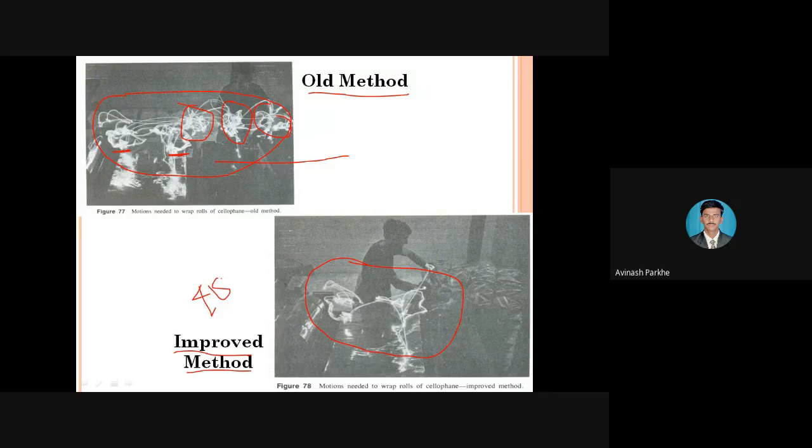So this is the use of the micro motion study, which is used to track small movements. We have to divide the activity into a number of activities, and the analysis of each activity can be carried out by recording the motion picture and the time required for that. All the information you get from the micro motion study concept can be represented using a chart. That chart is called a SIMO chart, the simultaneous motion chart. We will discuss the simultaneous motion charts in the next lecture. With this, today we will stop here. The remaining part we will see in the next lecture.